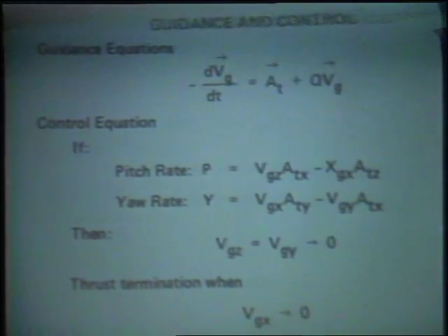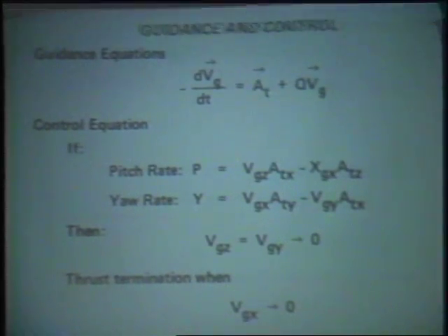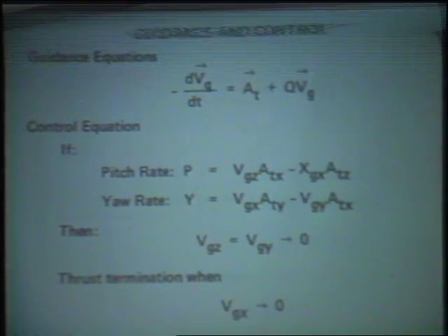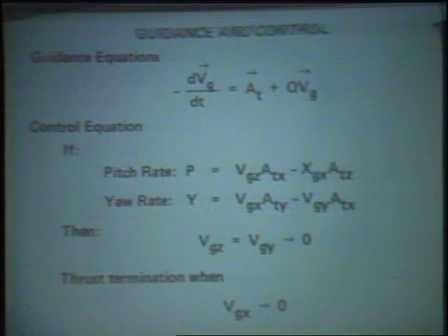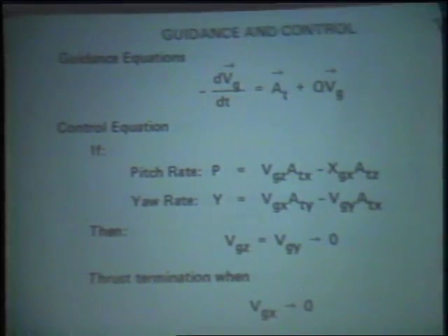Inertial guidance was necessary. The guidance computer proposed was a special purpose digital computer designed to solve the specific equations required for the guidance and control system. Now this may be too much detail, but the equations required here are these. For ballistic missile type guidance and control, there's what's called a velocity to be gained vector, which if you could add that velocity to the missile at any instant in time, it could free fall into the target. That VG vector satisfies the differential equation shown at the top here.